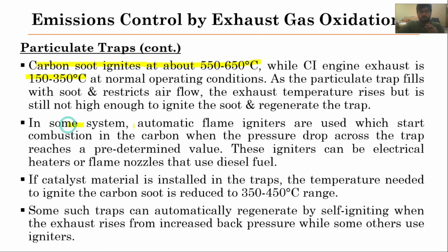So in some systems, automatic flame igniters are used when the pressure drop across the trap reaches a predetermined value. When the pressure drop has reached a significant value, these automatic flame igniters will ignite, and they will ignite those particulates which have been trapped in these particulate traps.